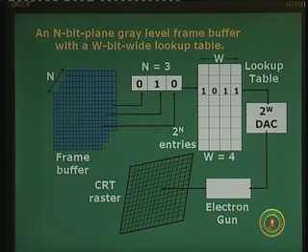That is okay, but what I mean is the contents of the register are acting as an index or a pointer to the lookup table entries, and the corresponding third row, the third content, will be picked out from the lookup table, which is w bit wide. Now this is interesting. Register was 3 bit wide, 8 possible values, but w is 4 bit wide.